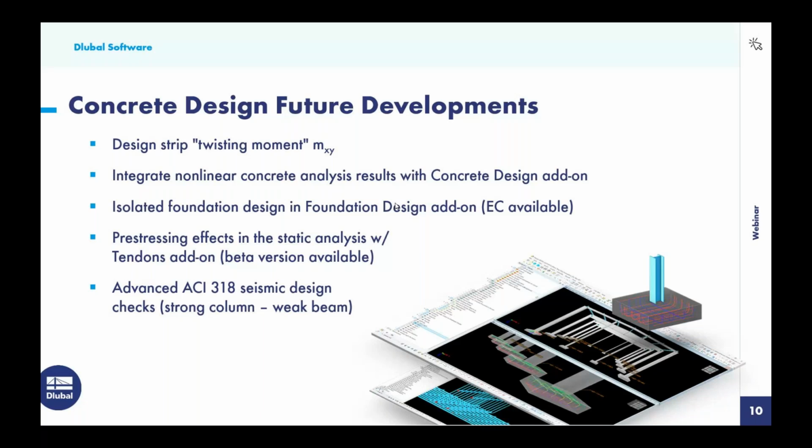So we will very soon release the design strip twisting moment consideration MXY. Currently those design strips are only considering moment in the one direction, the length of the strip itself, but we will have an additional option to also factor in the twisting moment. Again, that's a high priority that will be released soon. We also want to integrate, as I mentioned, the nonlinear concrete analysis results with the concrete design add-on, currently only available in the base program RFEM for the analysis only.